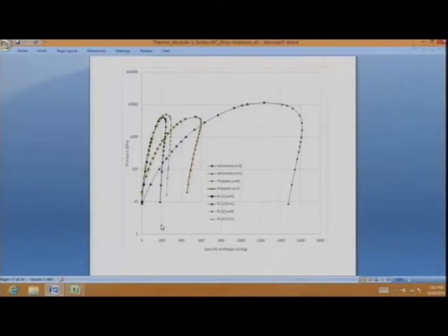We have propane, we have butane, we have R22, 23, 14, so many hydrofluorocarbons. And we start looking at all the properties and we find that two materials which are very similar in properties, we can substitute them with one another provided all the other things don't come in the way. For example, there is no corrosion or reaction with the oils, or it becomes toxic, then we won't use it.